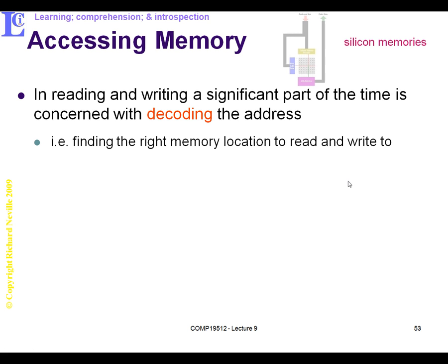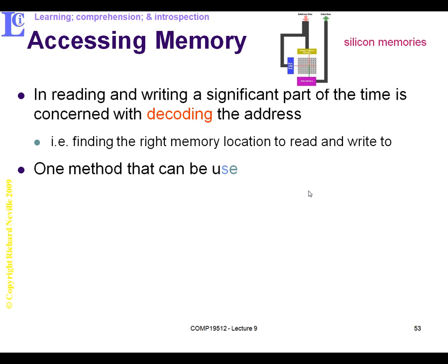time. So what we're actually doing here diagrammatically, a bit beyond the scope of the course, but you can see what takes time. First we take the address, and then we separate it into two separate addresses, the column address and the row address, and we clamp that to drivers which will actually generate the address and then find a particular data item and place it in the output data to be read or written to. So this process of setting up the address and finding that location takes time.